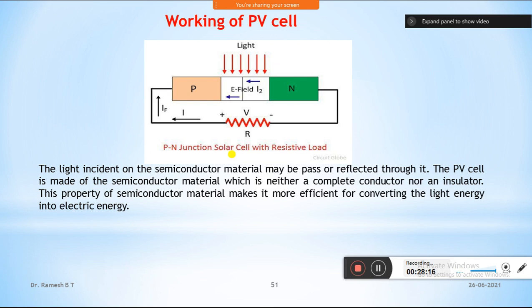Okay, so the working of PV cells, that is most important, how these PV cells work. I told you the PV cell directly converts the solar radiation falling on it into electric energy. The working of this PV cell is directly with semiconductor junctions. Here there is a junction formed by N type as well as P type. N type is because of excess electrons. P type means there is a deficiency of electrons, and that causes the positive and negative type of junction, and between these two there is an interface between P and N type. It forms the junction, and the junction is called a PV junction.